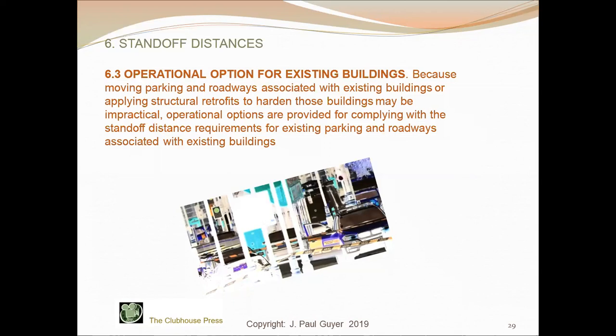And for roadways, the operational option is to prohibit parking along roadways within the standoff applicable distances of tables B1, B2, and D1. So there are operational options that may be needed when dealing with existing buildings, and you simply don't have the flexibility to move roadways and other buildings and things like that.